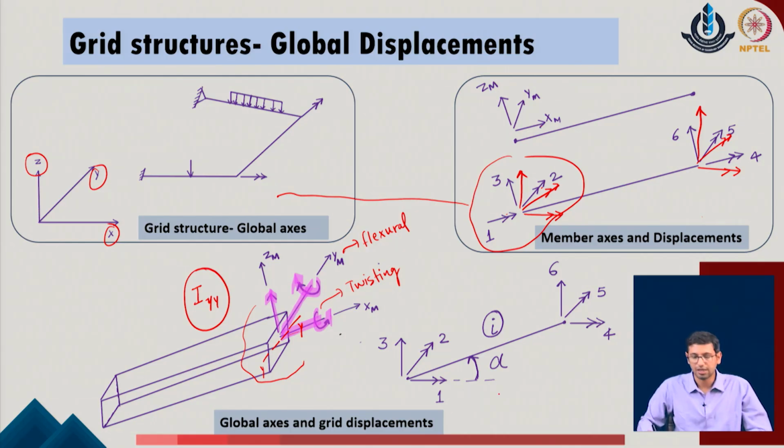Okay. With this idea in mind, we realize that at any given member there are two joints, say the joint j and the joint k. At both joints we get 3 degrees of freedom each: the two moment degrees of freedom, or the rotations of the given system, and one translation in the vertical direction. With this idea in mind, we can now go ahead with the calculations of the stiffness matrix of the system in the given problem.